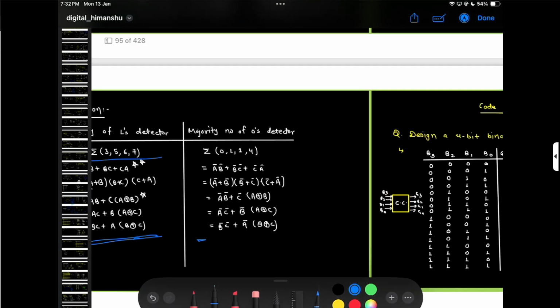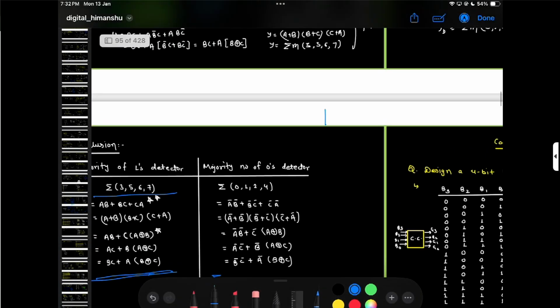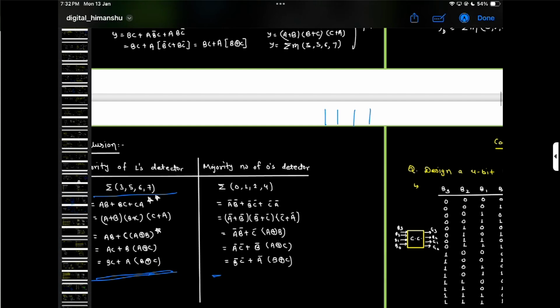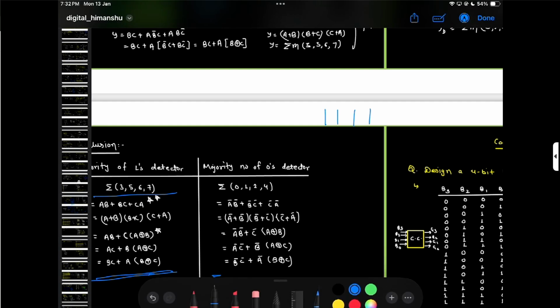And we know how to make binary to gray. Here, if my binary code is like this, how to make the gray code? Same as in the PDF again: just put the first one as it is, and then XOR this right here 0, XOR this right here 0, XOR this right here 0. So this is my binary and this is my gray.